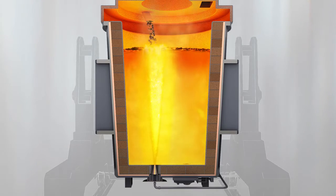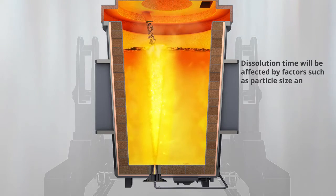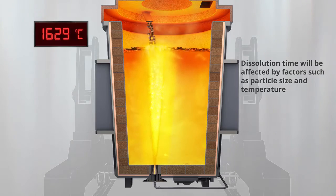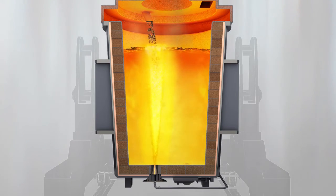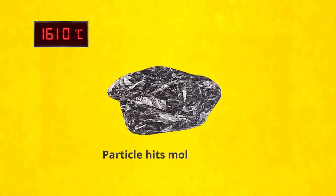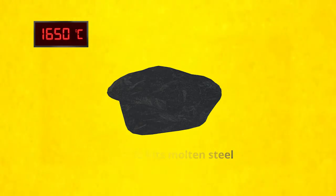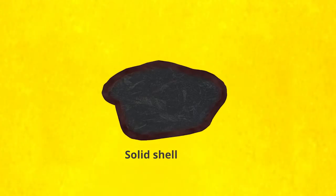Efficient recovery of niobium is closely associated with the melting and dissolution characteristics of the particles, and dissolution time will be affected by factors such as particle size, and even more so by temperature. Initially, as particles hit the molten steel, which is usually between 1600 and 1650 degrees centigrade, they actually chill and freeze the steel around them, forming a solid shell.